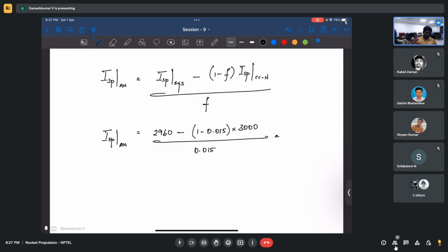Right. So the initial energy the gases had before entering the combustion chamber will be reduced slightly, because some of it was taken and used for your work, right? In that way it might reduce the chamber pressure or the chamber temperature by a little bit, and so ISP gets affected, but that is different. If you just look at the cycle and the nozzle part, the staged combustion is going to be more efficient.